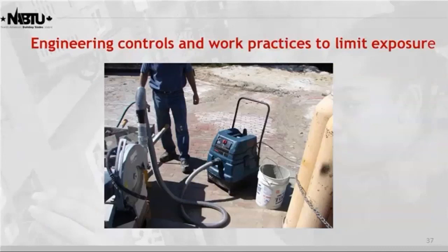It's a very good system, by the way. It's only for one tool at one time, so you cannot add another length of hose to it. You're going to lose its efficiency and that kind of thing, like we mentioned. But it's one tool, one vacuum. So a lot of training goes involved. When are you going to change the filters? How do you change it? So all those things have to be covered in your training program.